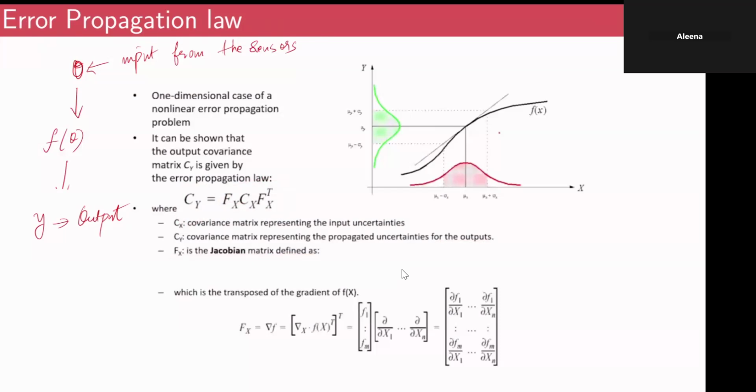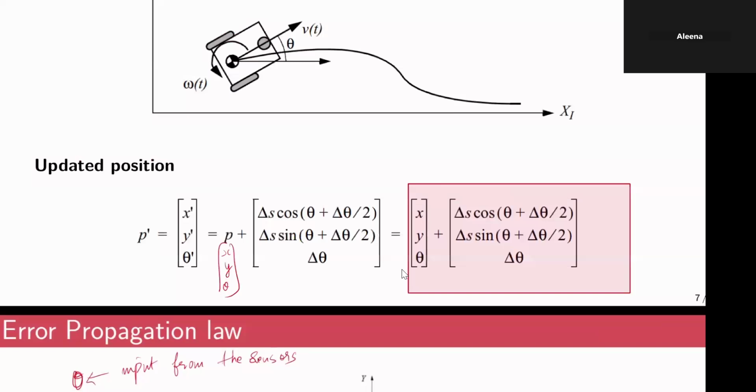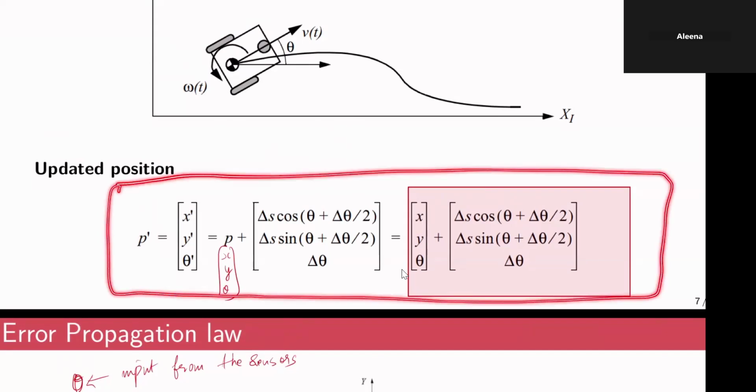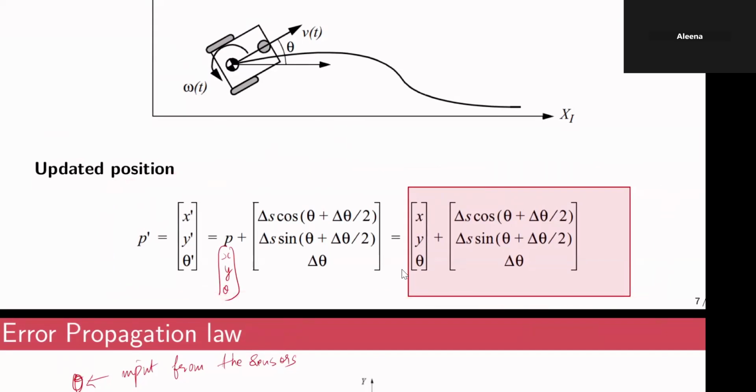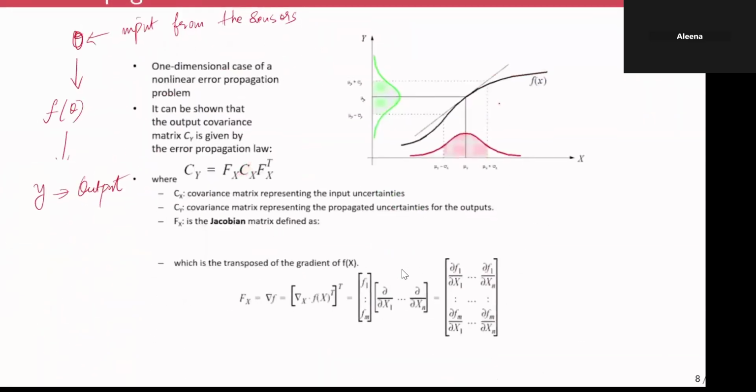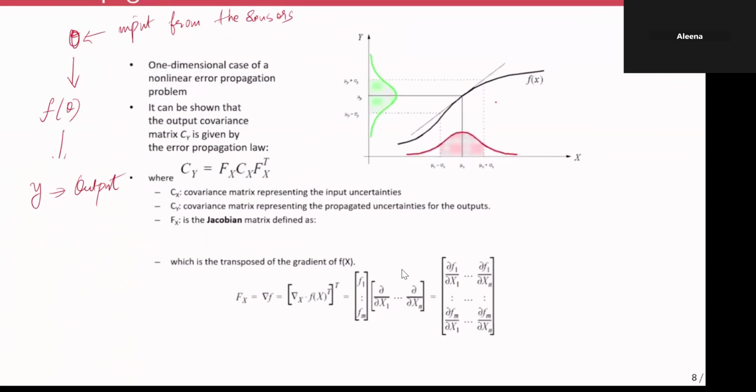So earlier we have actually considered the model, the kinematic model of the robot, like so. The Jacobian is nothing but the partial derivative of this vector function with respect to the quantity that we are trying to measure. So the Jacobian matrix is nothing but, if you have a vector function like this, f1, f2, f3, and your coordinates are theta 1, theta 2, theta 3,